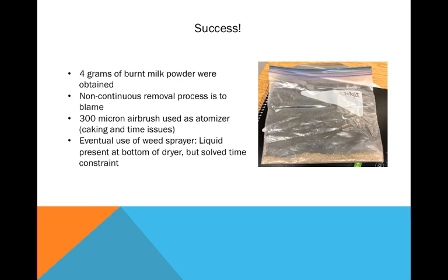At first, the 300 micron airbrush was used as the atomizer, but after 2 hours of testing, only 1 gram of milk powder had been collected. Milk began caking on the nozzle so that it would not spray properly. Also, since the airbrush created such a fine mist, it took a very long time to get through a relatively small volume of milk. Eventually, a weed sprayer was purchased in an effort to collect enough particles to sieve.